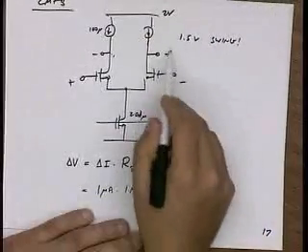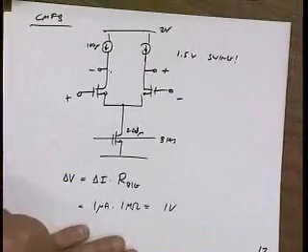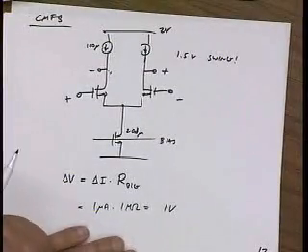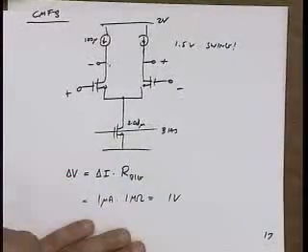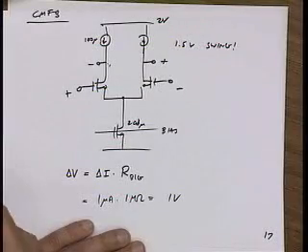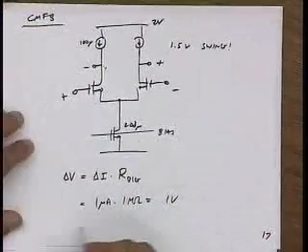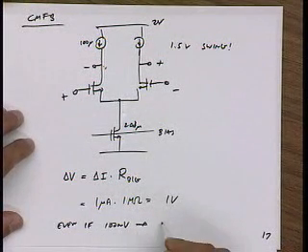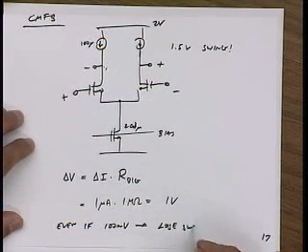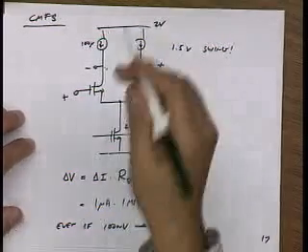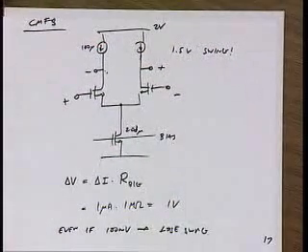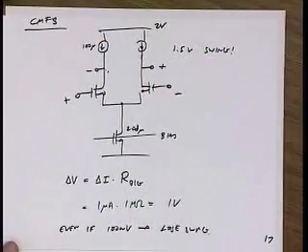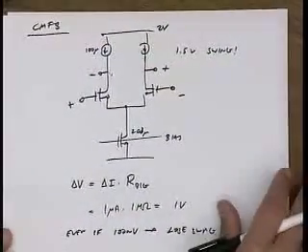So now if the swing is 1.5 plus or minus 100 millivolts, right? That's not good. Well, it's going to be minus always, right? So you're losing swing. So basically, even if this is 100 millivolts, you're going to lose swing. And if you had a 10 volt supply, you wouldn't care. But if you only have 2 volts, swing is very precious because it's dynamic range. The only way to win back that dynamic range is to dissipate power.